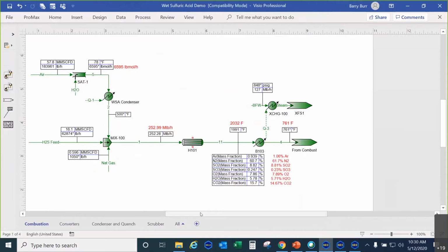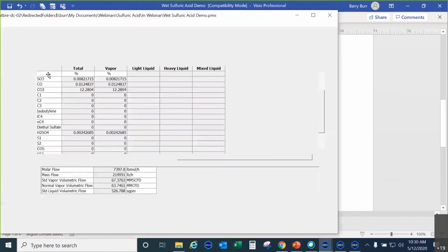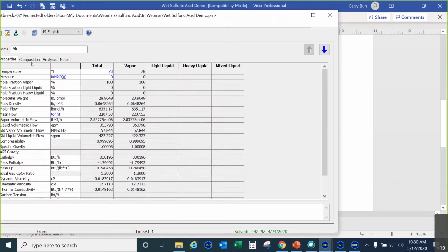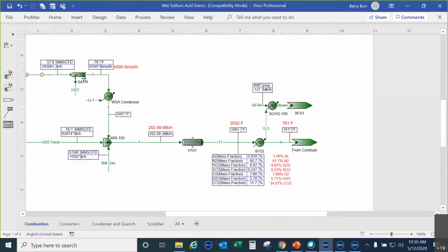Just like in the spent sulfuric acid, here we just have one burner. They may really have two different burners, but we're simulating it as one burner right here. So we're taking air, and we're just setting the airflow to match the plant's airflow. In this case, we're not trying to reach a target. They're probably trying to reach a target oxygen content in the outlet, but I just saw the measured flow rate and used that.